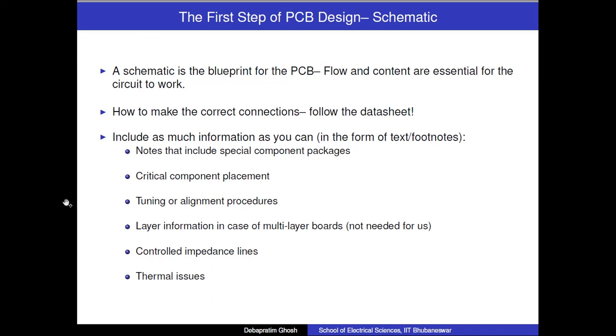So now, how do you get started with designing PCB? Now PCB is to be designed once your circuit is ready, your design is ready, and you know that your design is working. You must have tested it either through a breadboard or some simulation. So the first thing to do is to create a schematic. Now the schematic is a blueprint for the PCB.